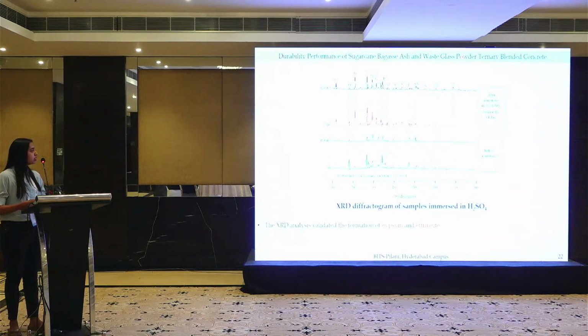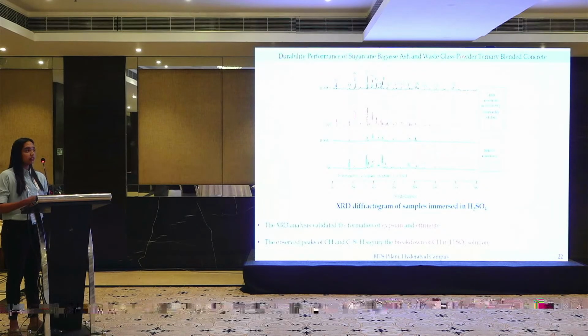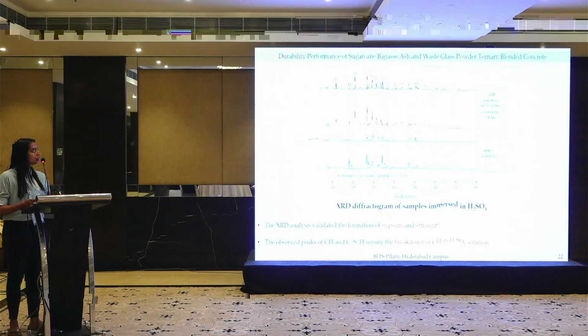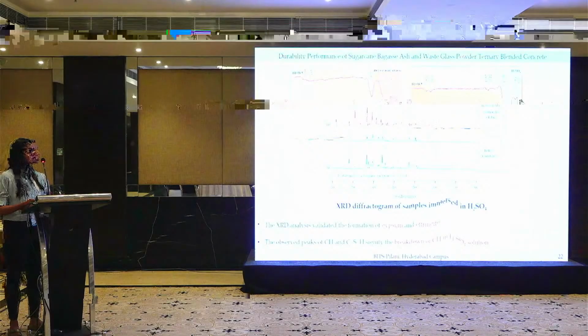So here also you can see the XRD analysis, the formation of gypsum and ettringite, and observe the peaks of CH and CSH, the breakdown of CH when the specimens are immersed in H2SO4. This is FTIR spectroscopy of samples immersed in H2SO4.